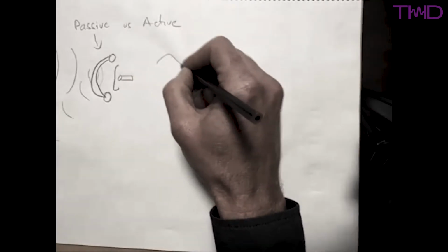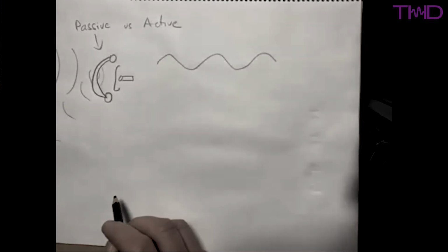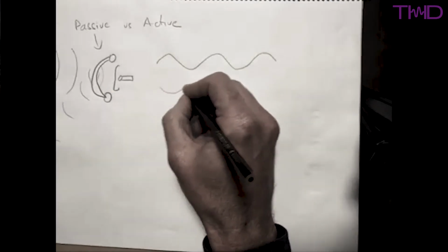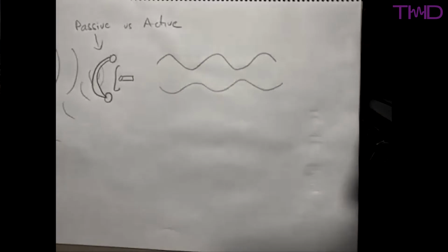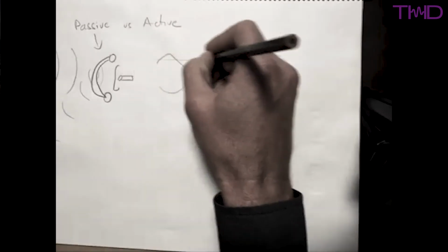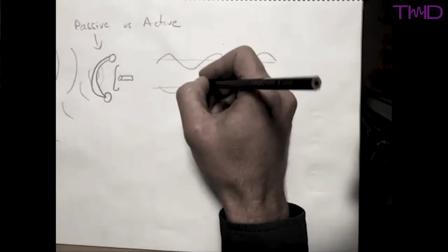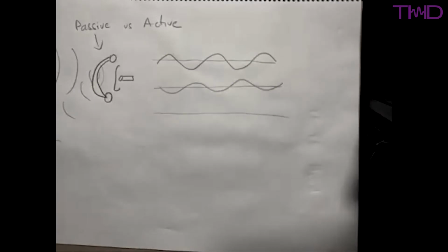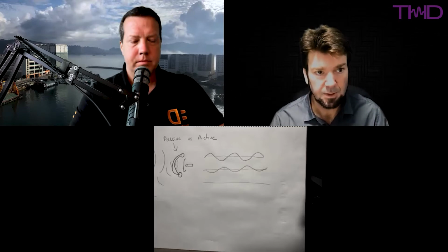So what active noise cancellation means, the principle is called the superposition of sound waves. What happens is you have some sound wave, and we'll draw it like the old sine curve, like that. If you have some sound wave traveling through the air, and you mix it with something that's equal and opposite, the pressure from those two sound waves add together, and you have positive and negative. Adding the positives and negatives, you'd end up with essentially zero pressure. Right. So that's the principle. What you're trying to do is have some generator that produces the equal and opposite sound pressure as the wave you're trying to cancel.